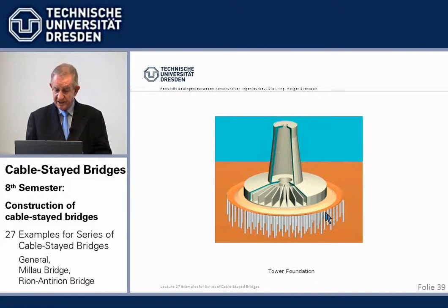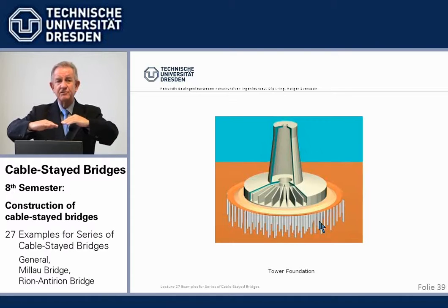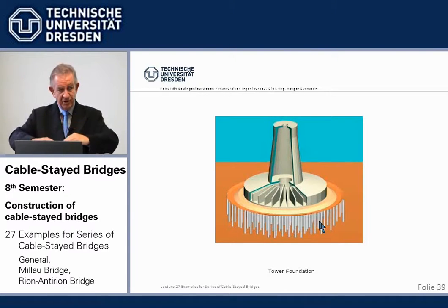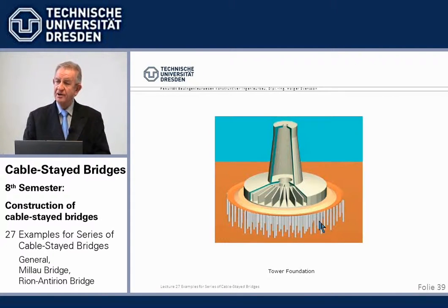And then underneath this differentiated layer of gravel, there are steel piles, but they end at the top of the soil. So they are not piled foundations, but they just reinforce the soil underneath, but they have no connection to the foundation itself, not a piled foundation. It's a reinforced earth in effect.